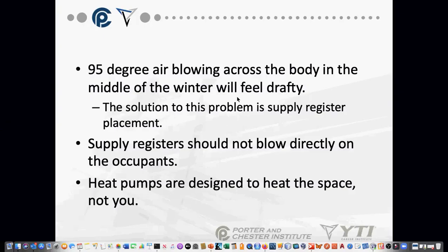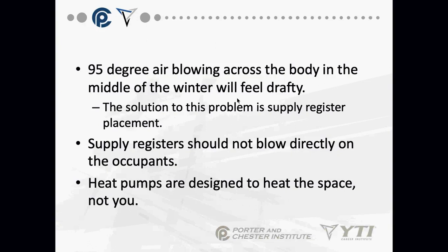95 degree air blowing across the body in the middle of winter has a tendency to feel drafty. The solution to this is that we're very careful about where we place supply registers. Supply registers should not blow directly on the occupants. Heat pumps are designed to heat the space, not the person.